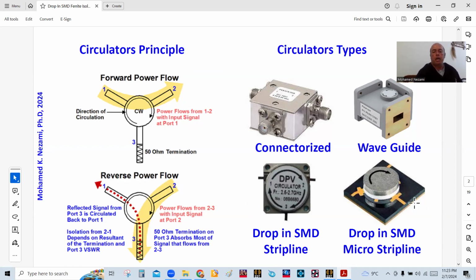The difference is that this is completely planar where you have a substrate, so you need to install this on a board. You either print the transmission line alongside the edge in here and lay it on top of another PC board, or you make a cutout in the carrier PC board and just drop this in and jump solder this to the 50 ohm traces, or to the termination in this case, if you're trying to use it as an isolator.